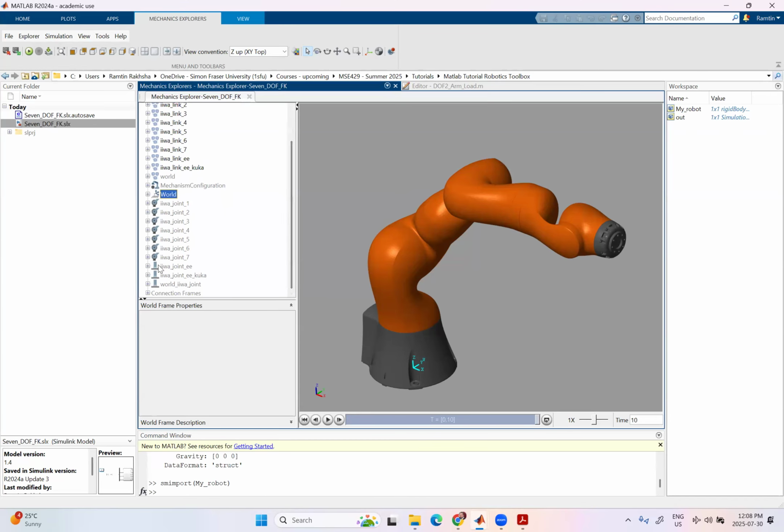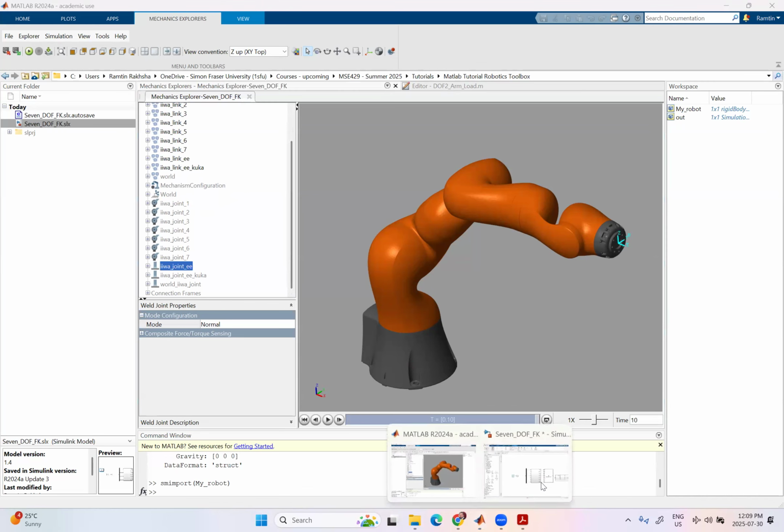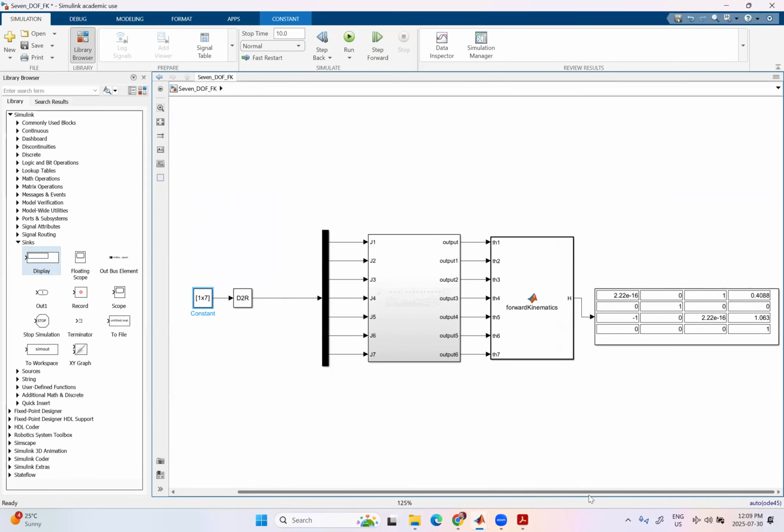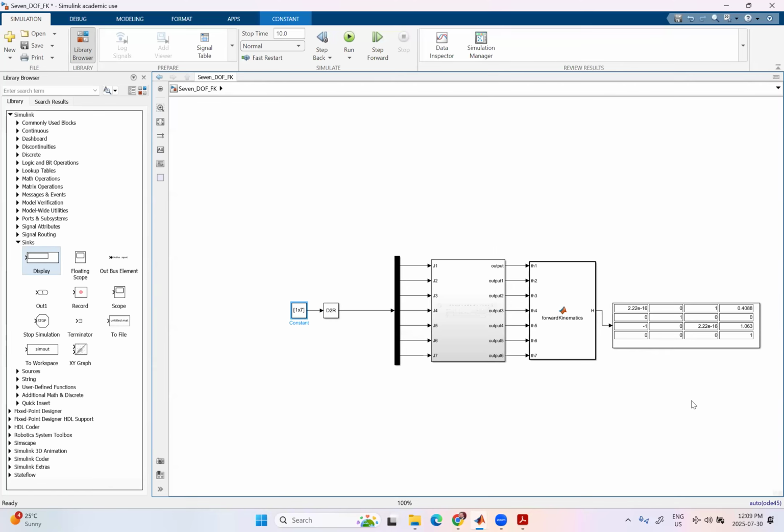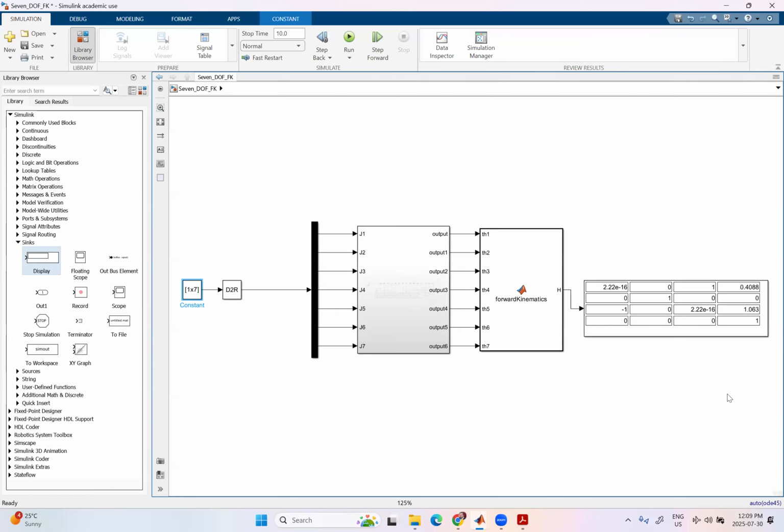And then let's say my end effector z is upward, which means if I go and check my matrix here, I should get 1, 0, 0. That's obviously a 0, that's a numerical error, right? So look at that. I get 1, 0, 0. That means the initial x-axis of my end effector is now aligned with the z-axis of my base. And that's how you can keep track of things and see how your end effector frame is changing. So that's an easy way. Perhaps if we knew this on day one, we wouldn't have gone through all the steps for your projects, but that was needed. Now you can easily understand this.